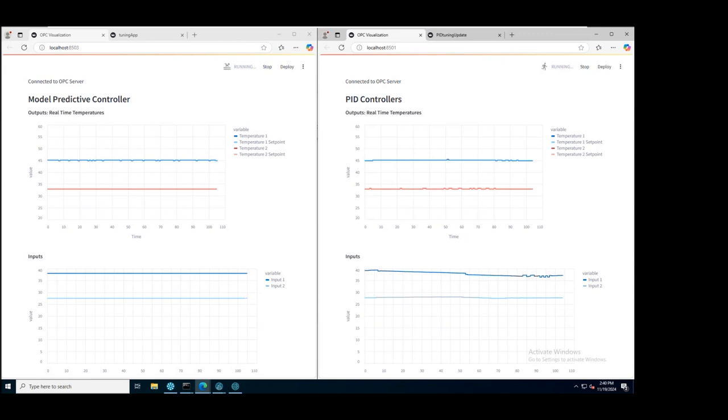So first and foremost, model predictive control is a multivariable control technology with emphasis on the multivariable part, meaning that multiple input variables and multiple output variables are manipulated at the same time. So we manipulate a large set of input variables to control a large set of output variables instead of segmenting them into single PID loops and associating one-to-one, right? And secondly, as the name MPC or model predictive control suggests, we use a model to predict how each of these input variables affect every single output variable.